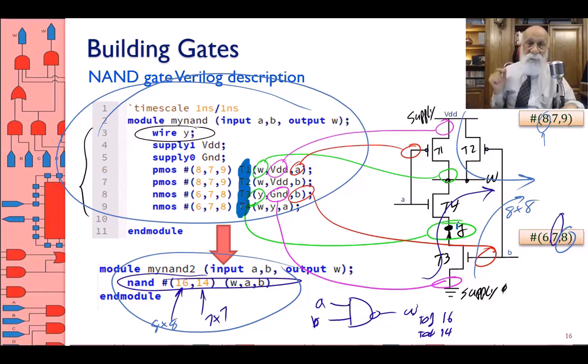And this is exactly what I have done here, except that this is not very, very complex. I could do that in a few minutes by just looking at the diagram. I encourage you to go in, type this in Verilog, and simulate it. And then you will be seeing the 16 and 14, I hope so, as the worst case delay for 1 and for 0.